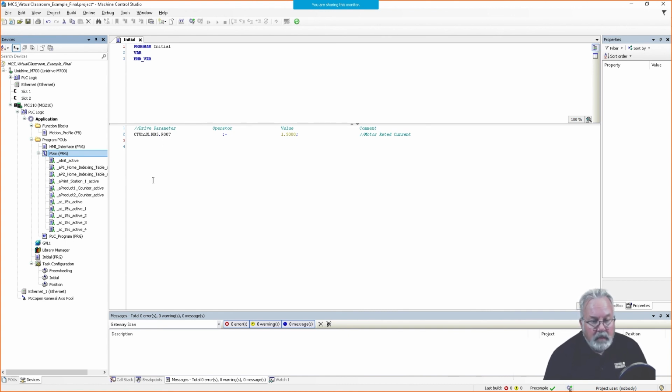So if clock task 0 is 4 milliseconds, clock task 1 would need to be 6 milliseconds, 8, something like that. So you set them up in ascending order with higher, slower times for each clock task, and clock task 0 is the highest priority clock task. Does that make sense? That makes sense, yes.